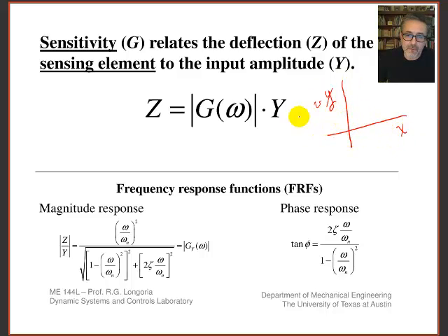Or the other way around when we do a calibration, right? We want X versus voltage, but you know what I'm talking about here. The output is a function of whatever that input is. And that sensitivity, usually we have some nice constant, linear line, and that slope right there is some calibration constant.